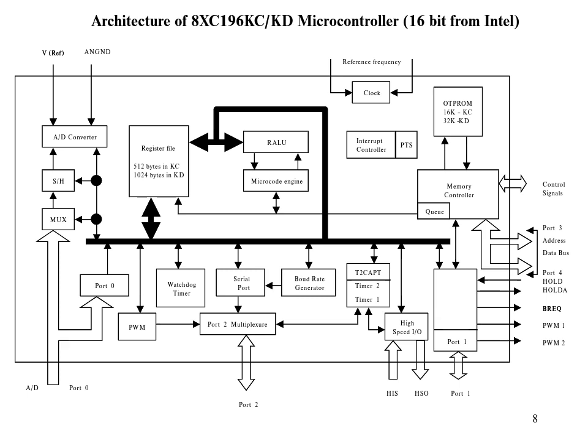The last slide was the CPU, and this slide is the microcontroller. As I have mentioned, within the microcontroller you have additional building blocks such as PWM, analog to digital converter, digital to analog converter, and also the IO port, interrupt controller. On top of the basic building blocks that should be there in the CPU, this microcontroller has additional building blocks which are required in order to implement control systems.